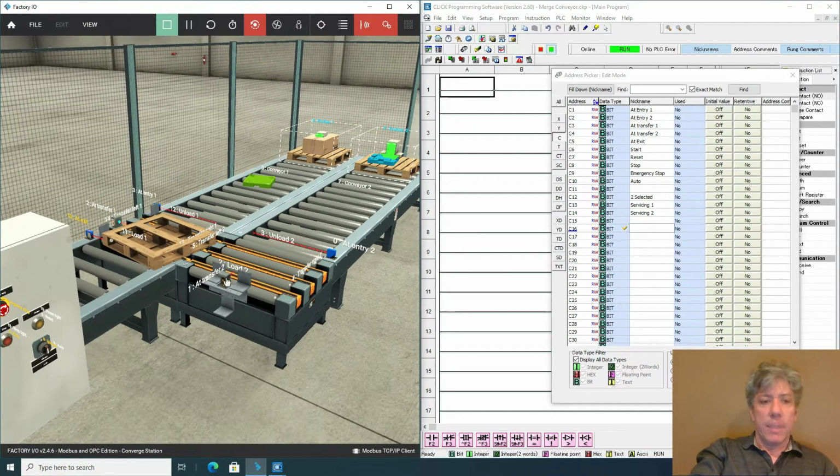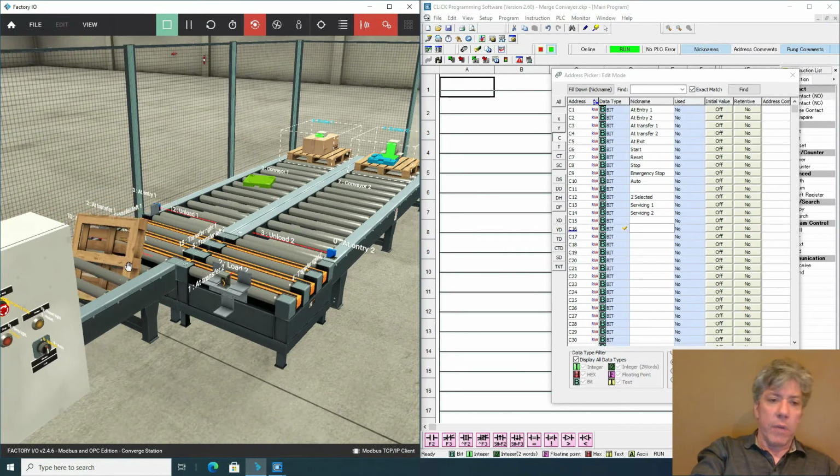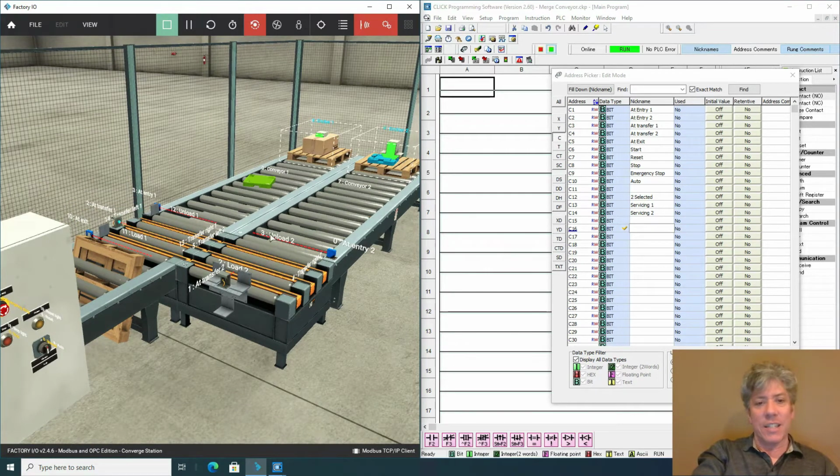So I've got to get the pallet over to transfer conveyor 1, and after that, I got to shut off these transfer conveyors, turn on the load conveyor, or the load on the transfer, and that way the pallet goes on, hopefully not through the conveyor like that. See, so there's a sequence of events, right? I got to move the pallet over and then get it off. So remembering where I'm at in that sequence will be really important.